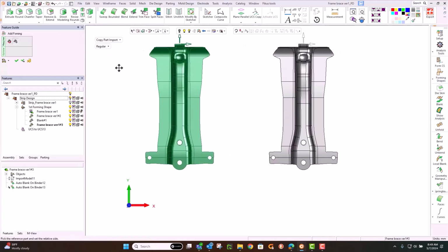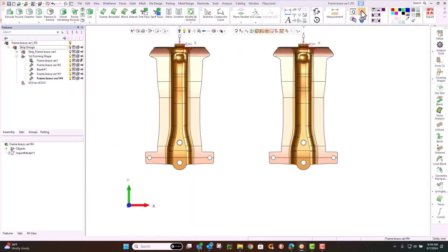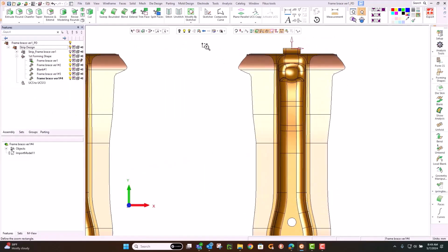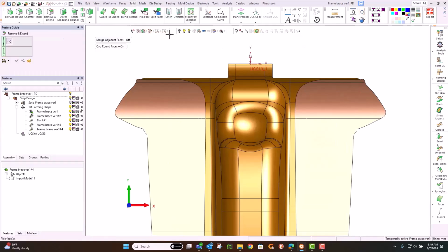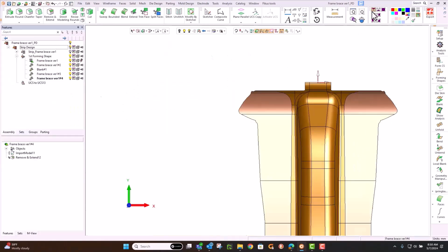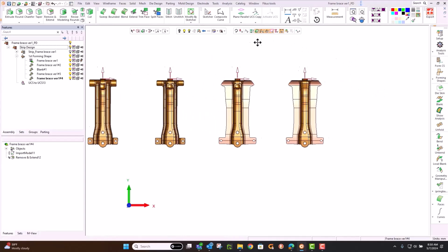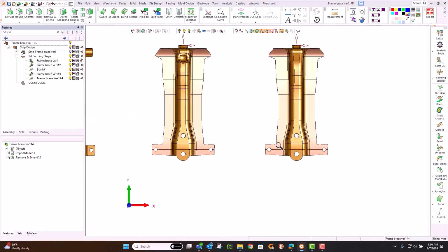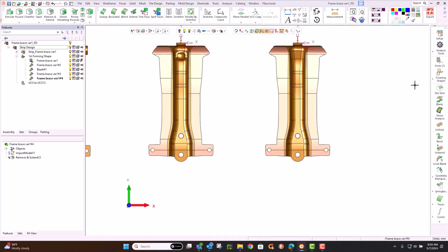Right, so perhaps that was placed in because we needed to stretch that area, understanding that there's the wrinkle tendency. Let's do that in one single step. So in this case, we'll go ahead and take that out of our sequence of operations. Now we've got our forming condition just for that particular dimple area. Moving on, we'll do another one.